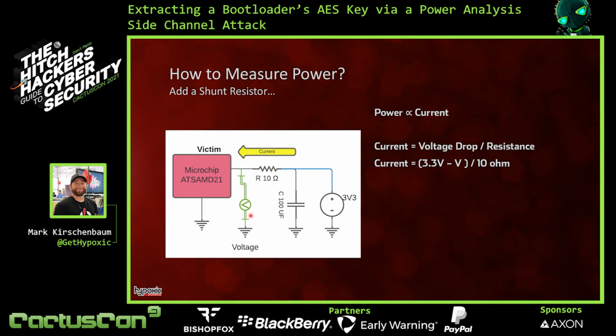So this voltage probe here is more or less going to be directly proportional to how much power the system uses. The measurement here is going to be directly proportional to the power that the system's using. Now, if we want to do this over time, if we want for each instance in T to measure the power being used, all we do is use an oscilloscope, and that will measure, at every acquisition point, what that voltage drop is, and therefore measure basically the power curve of the system.